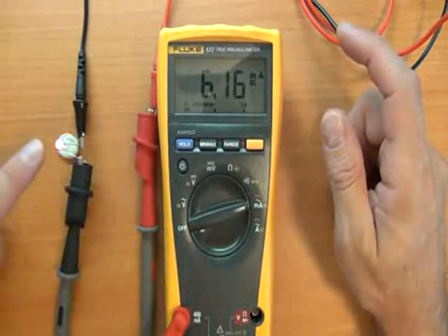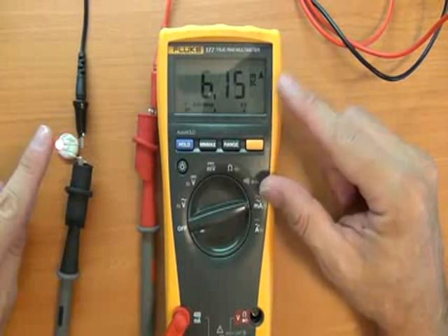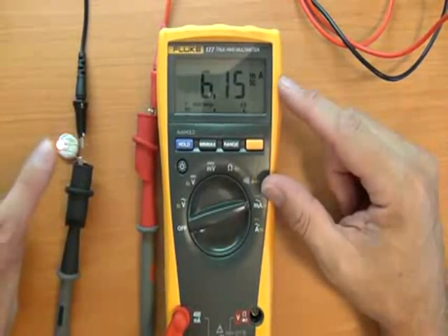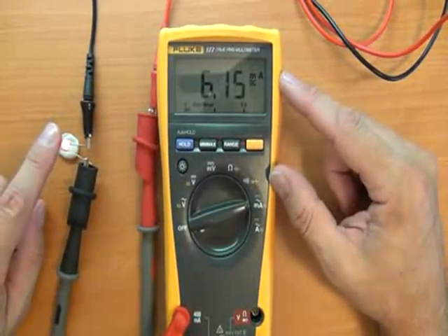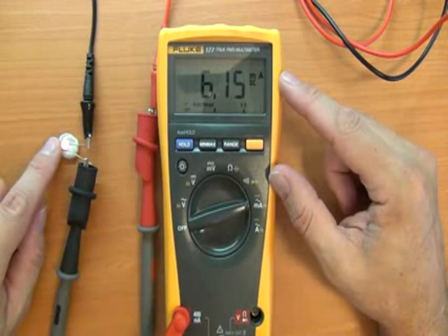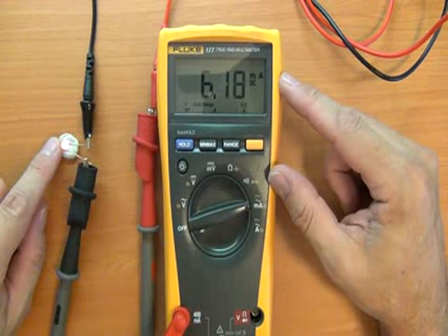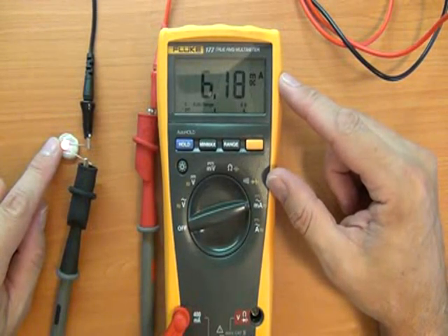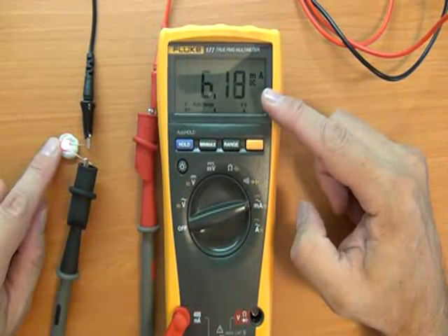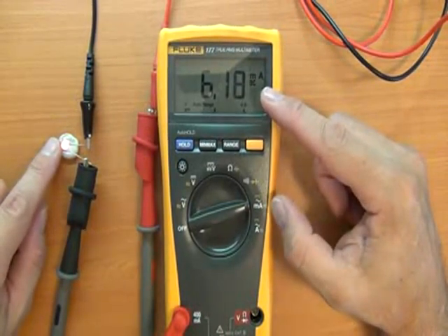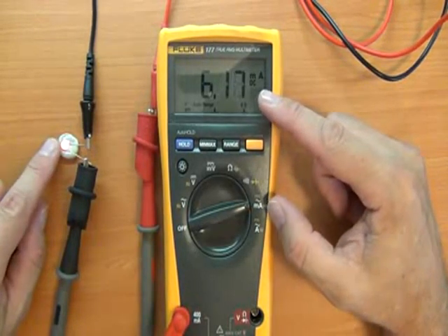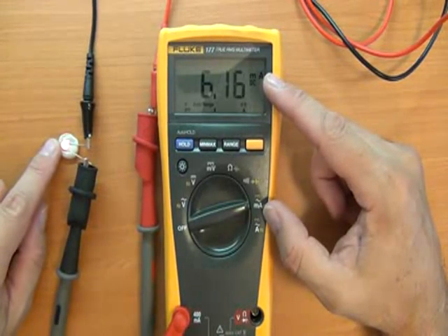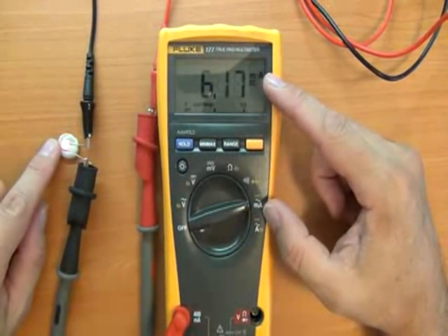We're forming part of that circuit, and that's how we can read current, or the volume of electricity being used by this LED. And that's quite an important fact, because later down the line, when we come to do some more advanced measurements like power consumption, you do need to know voltage, but the more important fact besides voltage is the current which is being used, the amount of electricity, because that can help you understand what size battery you need, what size solar panel you need, or how much power your house is using, or a particular appliance.